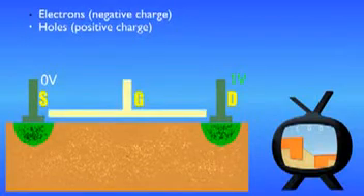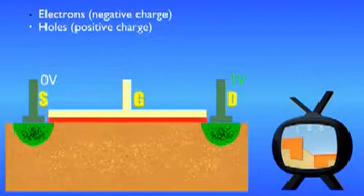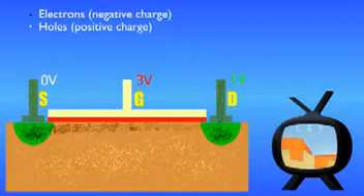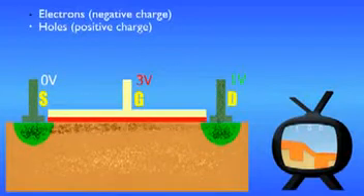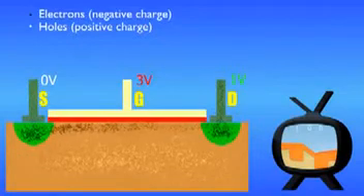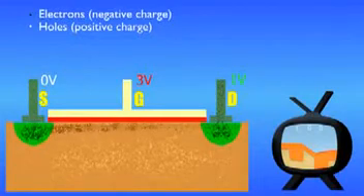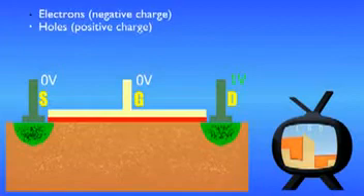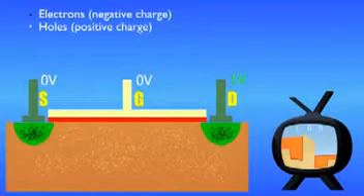The gate contact is made by using a highly conductive material separated from the semiconductor by an insulator. By applying a suitable voltage at the gate, the electrical charge can be attracted from the source. As a result, the barriers preventing the passage of the electrical charge are lowered, allowing a current to flow from the source to the drain. Under these conditions, the device behaves like a switch in its on state. If the voltage is not high enough to lower the barrier, there is no current, and the device behaves like a switch in its off state.